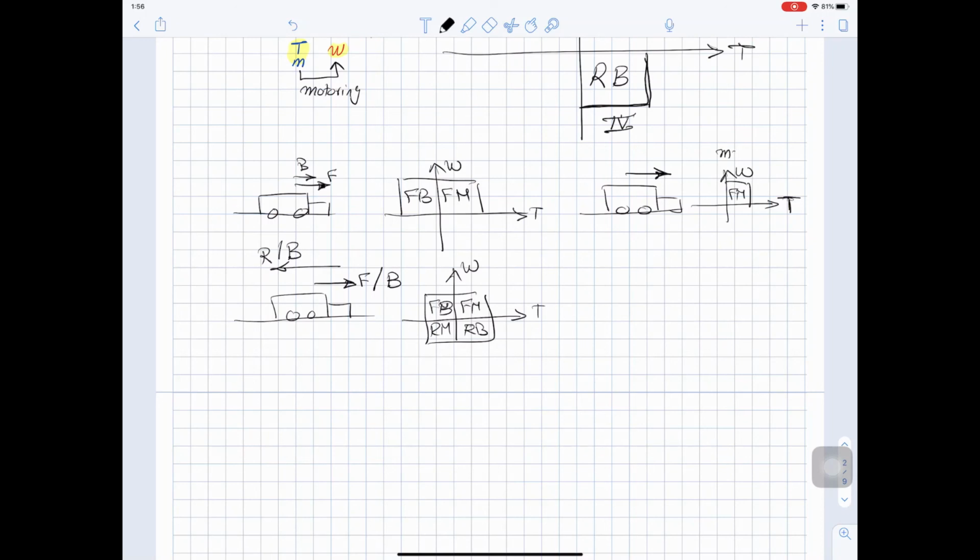We call this the motor drive. The motor drive can be a 1-quadrant motor drive, or 2-quadrant. And for 2-quadrant, it can be the forward 2-quadrant or the reverse 2-quadrant. This is reverse braking, reverse motoring. So the motor drive here is 2-quadrant, here is 1-quadrant, and here is 4-quadrant. So 2 quadrants means you can accelerate it in one direction and brake it in the same direction.